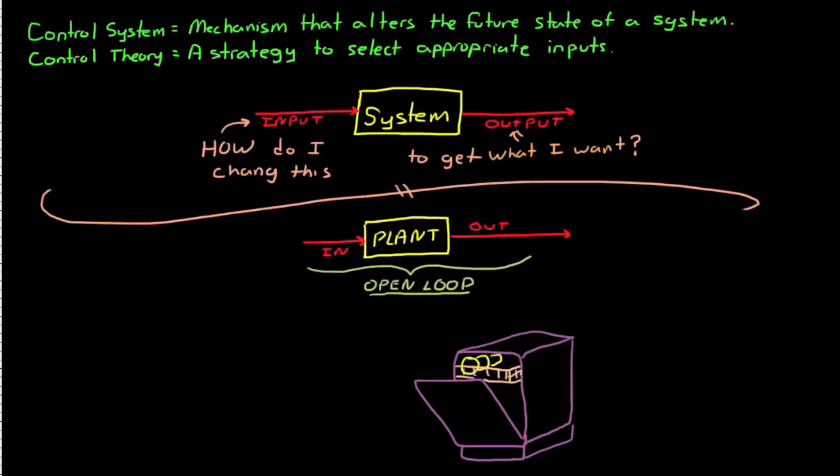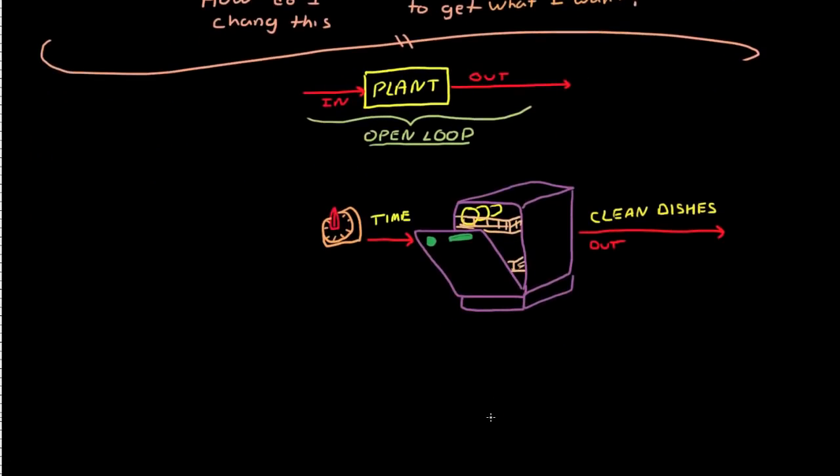For example, a dishwasher is an open loop control system. The goal of a dishwasher, which is the plant, is clean dishes, which is the output. Once the user sets the wash time, which controls the time to clean the dishes, the dishwasher will run for that set time. Now, this is true regardless of the cleanliness of the dishes. If the dishes loaded were clean to begin with, the dishwasher would still run for the prescribed time. Further, if you loaded the dishwasher with 10 plates full of cake, the set time might not be enough to clean them.